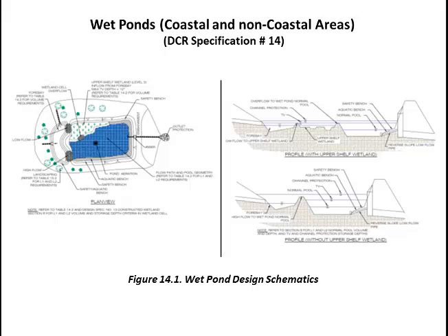Figure 14.1 gives the schematics of a typical wet pond. This includes forebay, aquatic benches and permanent pool, as part of the pond. Wet ponds are acceptable for use in the coastal plain, where the water table is within 4 feet of the land surface. Wet ponds, like extended detention ponds and constructed wetlands, are the final elements in the roof-to-stream runoff reduction sequence. They should, therefore, be considered only if there is remaining treatment volume or channel and/or flood protection volume to manage after all other upstream runoff reduction practices have been considered and properly credited.